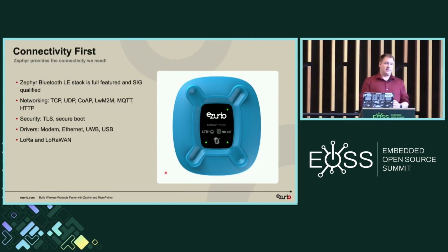Connectivity is first for us, as we are primarily a wireless company. We need all kinds of wireless connectivity. So Zephyr has a fully qualified Bluetooth stack. It's certifiable. It's up to date. We get all the networking we need, any protocol we can ever want. We get security with Mbed TLS. And as I mentioned, drivers: modem drivers, Ethernet drivers, and LoRa and LoRaWAN. And it all works and it's reliable, and that's what Zephyr gives us.